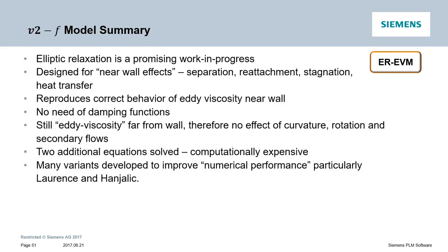To summarize the V2F model, this model is designed to capture near wall effects like separation, reattachment, stagnation, and as a result it reproduces correct behavior of eddy viscosity near wall without the need of damping functions. But still it's an eddy viscosity model far from the wall and is not able to capture the effects of curvature, rotation and secondary flows. Also, it's computationally expensive due to 2 additional equations, and the F equation still poses some challenges in terms of boundary condition implementations and convergence.